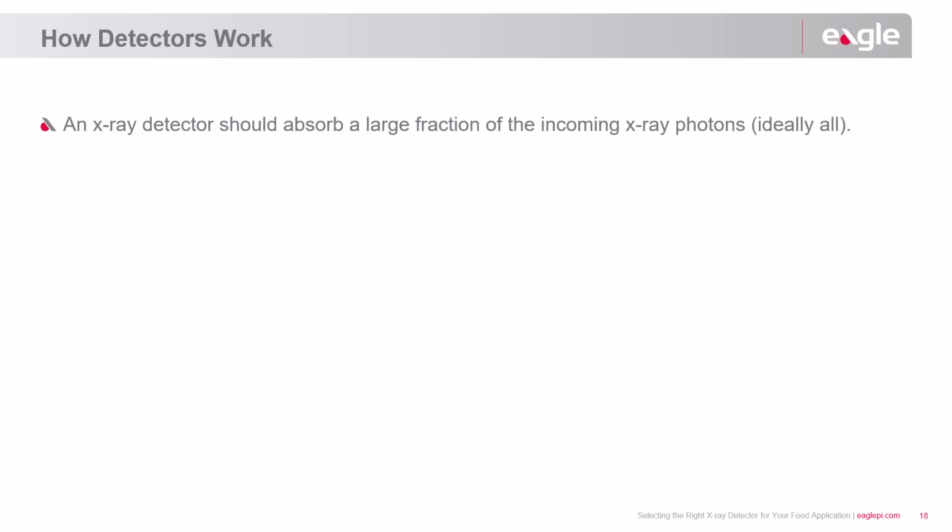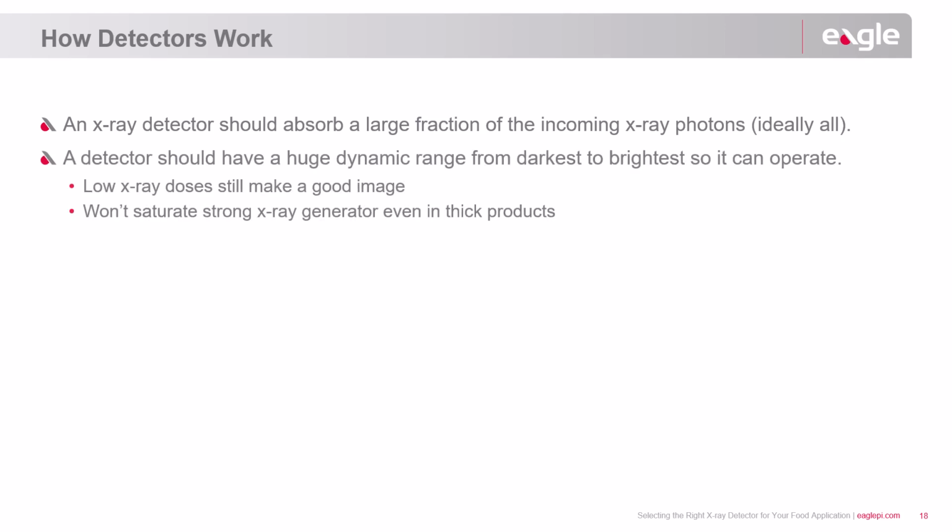Detectors should possess a very large dynamic range to capture the full spectrum of energy penetrating the product. This capability ensures that whether a product is exceptionally thick or extremely thin, the detector will not become saturated or underexposed, thereby maintaining image quality under all conditions.